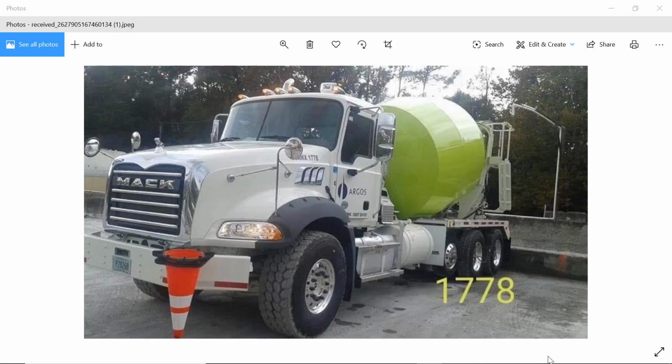Example 5. The example design mix calls for 1,620 pounds of coarse aggregate and 267 pounds, 32.0 gallons of water per cubic yard. The aggregate has an absorption of 2.50%, and the total moisture content is determined to be 6.53%. Calculate the adjustments to batch quantities per cubic yard. Figure the water adjustment in pounds and gallons. 1. Free moisture is equal to 6.53 minus 2.50, which is equal to 4.03%.